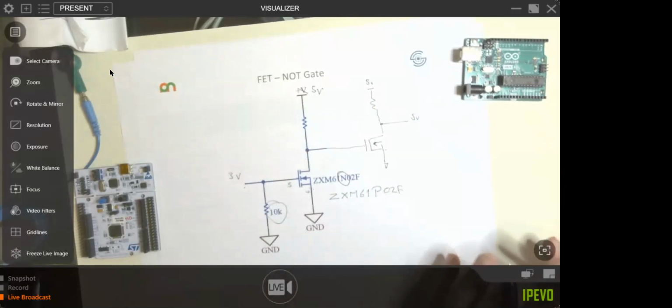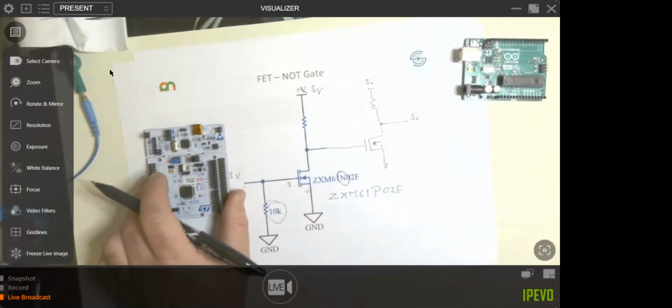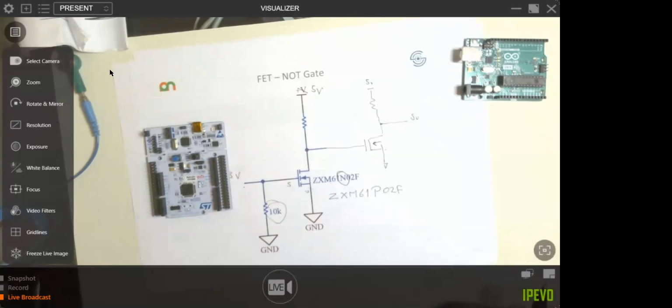One thing worth remembering is if you're driving anything from an ARM chip or any microcontroller, when you put these chips into reset, the outputs usually will be floating, so there'll be a high impedance. They're neither a high voltage nor a low voltage, and you wouldn't necessarily want your transistor to have an unknown voltage.